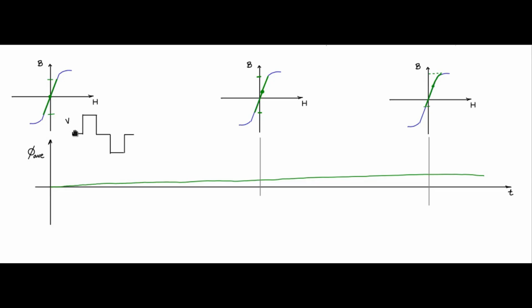We just now saw this V primary. And as it is swinging in the linear region, there is no change in the d phi by dt rate here, or even in this case, there is no change in the d phi by dt rate. So the primary voltage waveform will look essentially like this. Now, in this last case, where a portion of the flux operating region is moving towards the knee, the d phi by dt there is decreasing, and you will see a drop in the induced voltage across the primary.